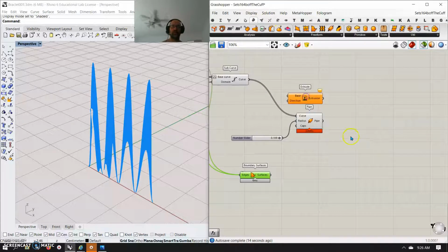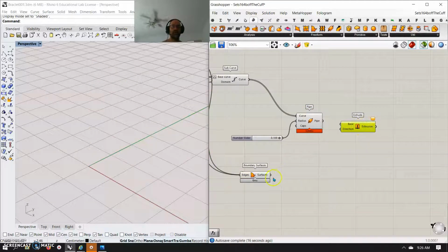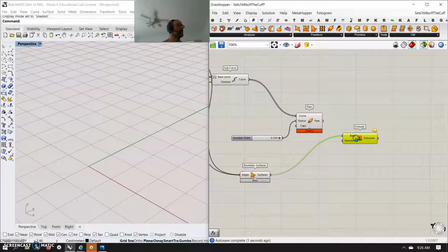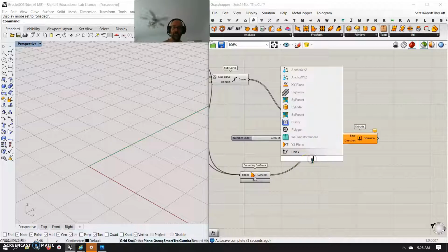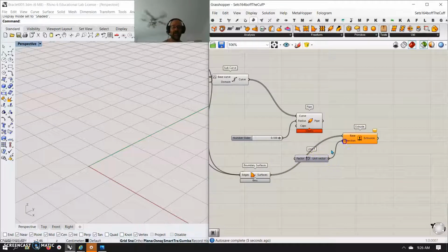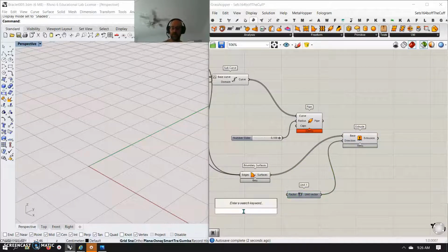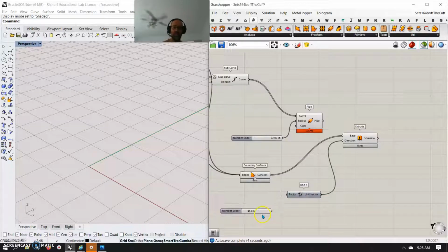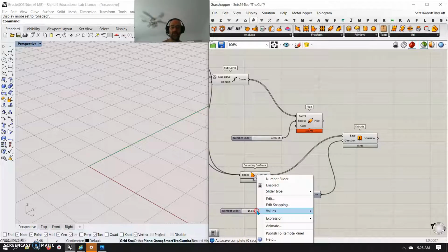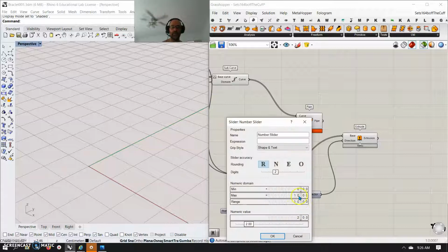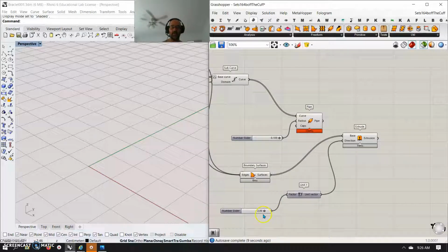I've got to look at my other script because now I'm mentally getting, I challenge myself a little too much. Let's take that surface as a direction, and we'll move that in the Y axis, and then I will make a slider to it. I'm just going to set up 2.00 as a slider, but the slider itself I'm going to go into and edit, and I want to be able to take that up to 3, down to 1, make that negative, and take that down to 3 in the negative. So now I can actually play off of positive and negative.